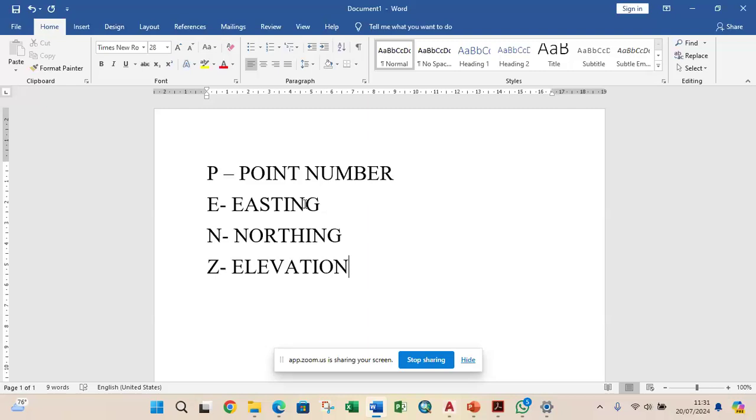So if a surveyor goes to the site and doesn't establish the right coordinate, or doesn't do a proper setting out of his instruments, and they plot the road, they will pick a location that you want them to pick. But once you are done designing and go for setting out, you see that it's taking them a distance away from that road. So the engineer needs to carry the surveyor along: this is what you have to work with. Let me know the datum you're working with. And what is that datum?